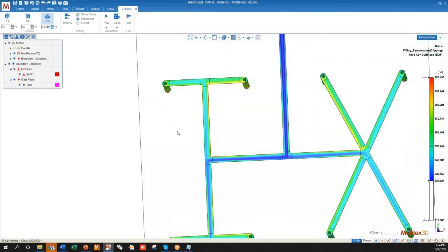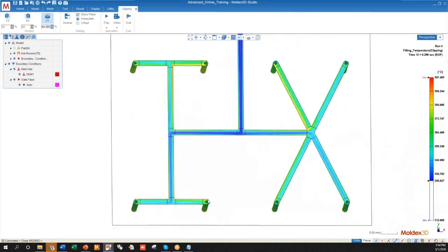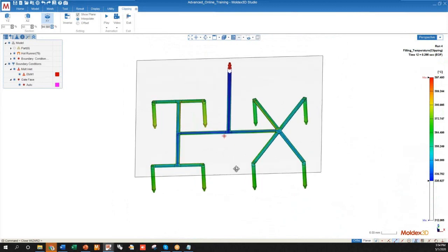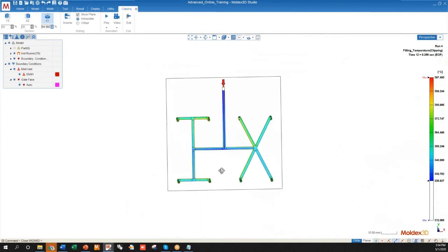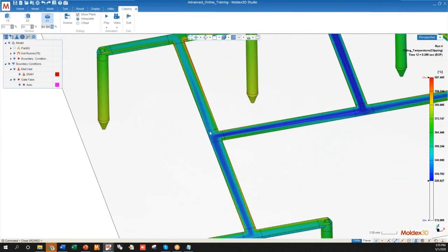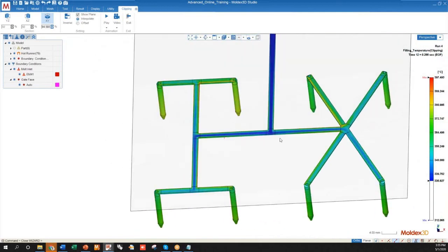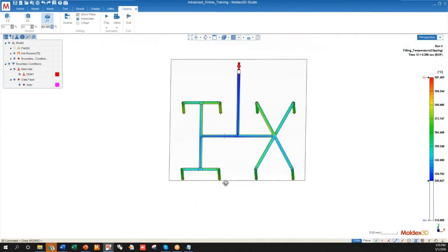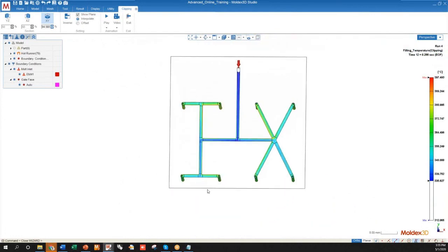But this shear heating problem is going to be apparent whether you use the line-defined or a geometry system. Both should be able to pick this phenomenon up. But the most important thing is that we're using the 3D solid mesh elements to calculate what's actually going on, rather than creating some junction assumptions, or just assuming that the melt flow creates some sort of pressure drop. We actually want to see what's actually happening with a 3D solid mesh.